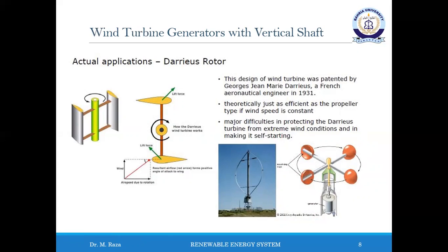This generates a net force pointing obliquely forward along a certain line of action. This force can be projected inward past the turbine axis at a certain distance, giving a positive torque to the shaft, thus helping it to rotate in the direction it is already traveling in.